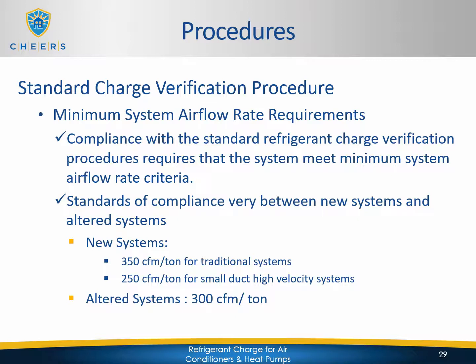Compliance with the standard refrigerant charge verification procedures requires that the system meet minimum system airflow rate criteria. Now these standards of compliance do vary between new systems and altered systems, as well as we may see different values modeled using the performance approach. So our default prescriptive values for new systems can be dependent on the type of duct system.